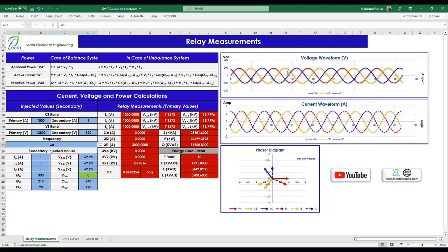Of course, as you can see here, this is the voltage and the current, and of course, the relay will take it as it is. That's why I drew it for you starting from 0. And you won't find the current here. Your current will start to be delayed because you set it to negative 30 degrees, meaning it lags by 30 degrees. Is that clear? It lags by 330, meaning it lags by 30 what? 30 degrees. Is that nice?